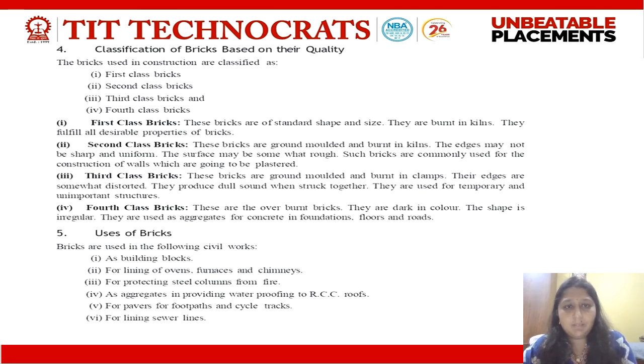Next, we would be discussing the classification of bricks based on their quality. The bricks used in construction are classified as first class, second class, third class and fourth class depending upon their quality. The very first one are first class bricks, which have all standard properties: good color, soundness, hardness, no scratching, no flaws and everything. The properties are desirable or up to the mark.